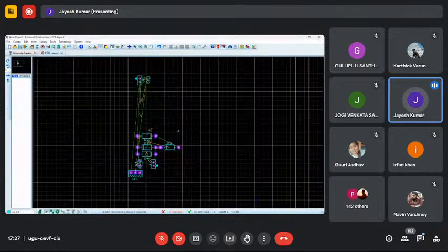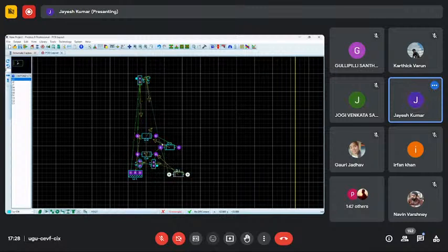While zooming in, you can see that my circuit is directly imported to the PCB layout. Now you have to set the components according to your need. So now I will arrange all the components a little bit. I start with the diode, first diode D1, then D2, D4,